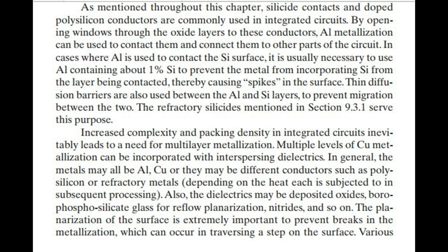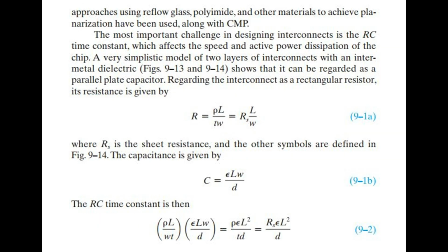The planarization of the surface is extremely important to prevent breaks in the metallization, which can occur in traversing a step on the surface. Various approaches using reflow glass, polyimide, and other materials to achieve planarization have been used, along with CMP. The most important challenge in designing interconnects is the RC time constant, which affects the speed and active power dissipation of the chip.